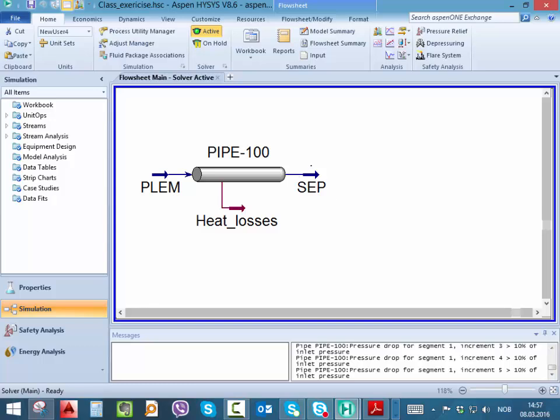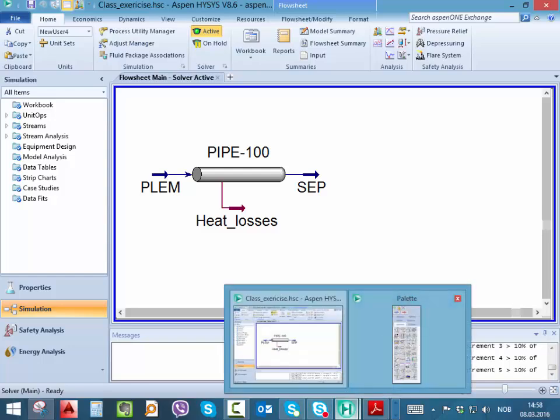So really what you want to do in the industry is not to be putting numbers in one by one, because otherwise you spend your whole morning and then you cannot do anything else. You want to go home early. So for that we're going to use some kind of solver. If we had the same problem in Excel, what do we use? Solver. We say, solver, please set this pressure to 30 by changing this pressure. Luckily, Hysys also has a solver that is called Adjust.